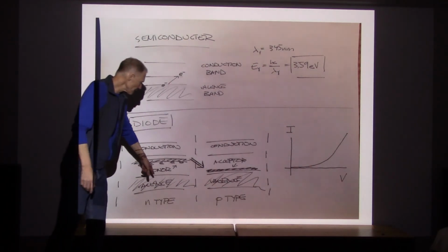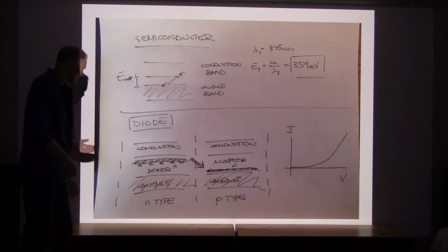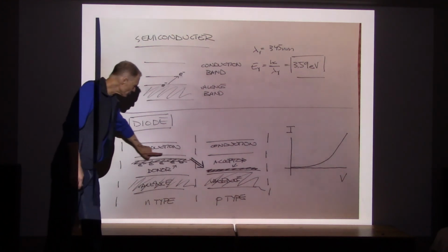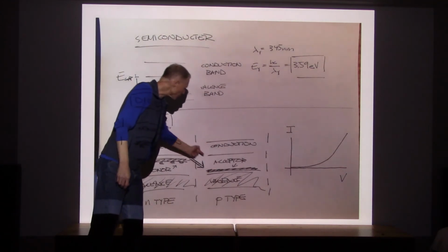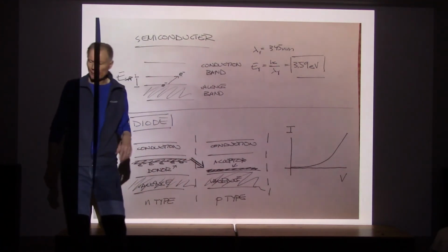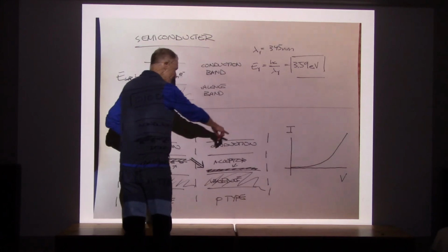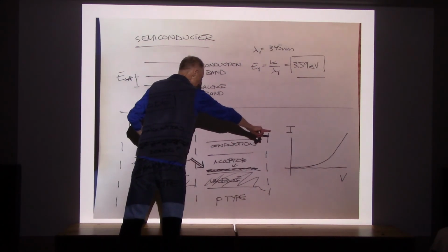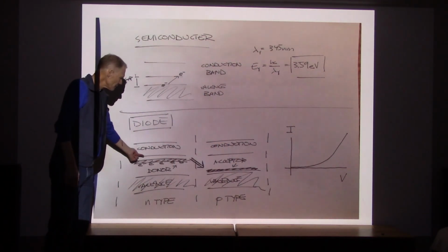So here's the n-type material, p-type. And again, what's going to happen in a diode is if we push electrons into the n-type, they're going to go into these donor quantum states, and from there they can cross the boundary and easily drop into the acceptor quantum states, which have been opened up. The p-type is attached to the positive terminal. The positive terminal is pulling electrons out of these lower states, while the n-type is seeing electrons coming in to these upper states.